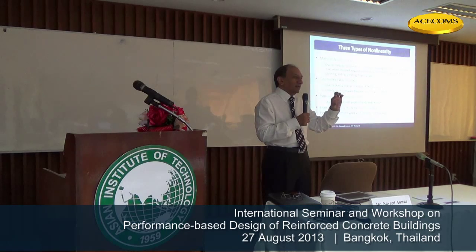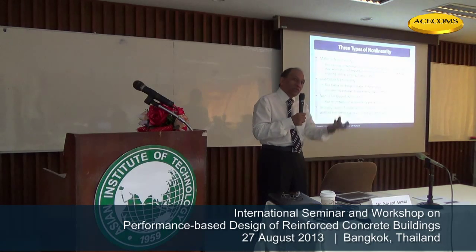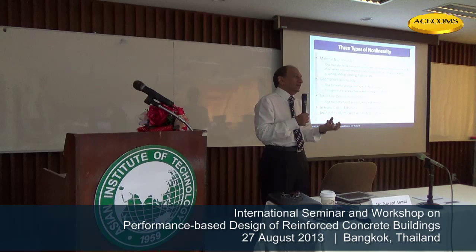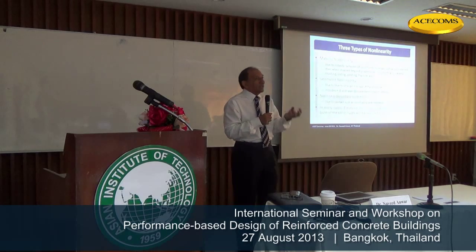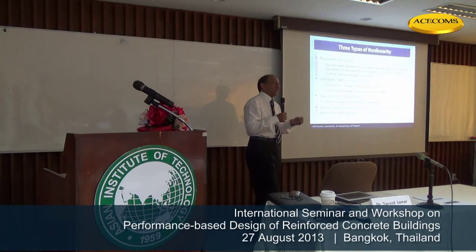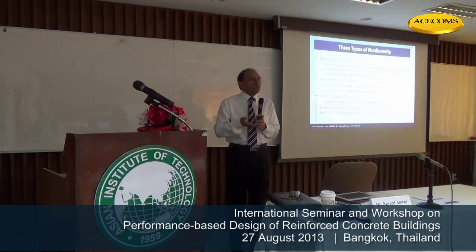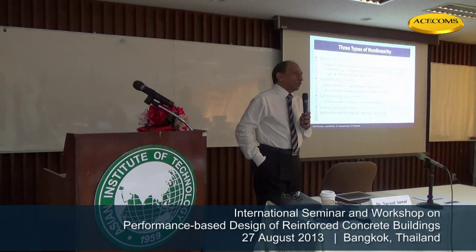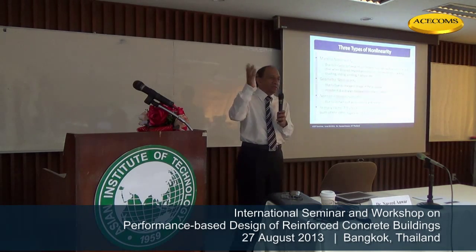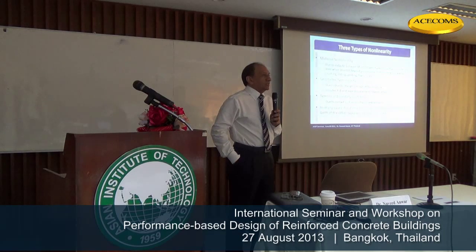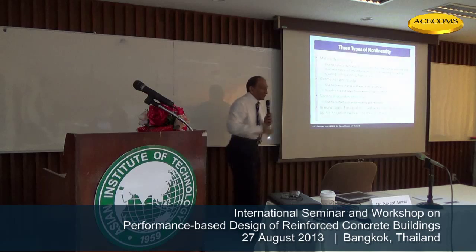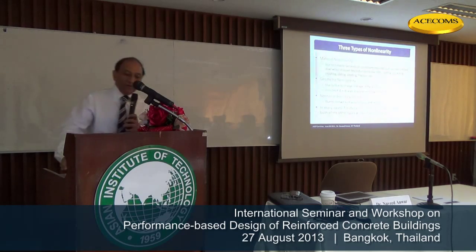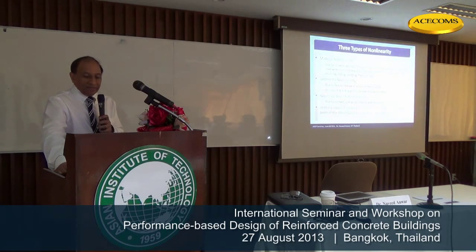That must be modeled. In a normal model, the foundation will pull the structure down. In reality, it cannot pull it down, unless it is a tension pile or something. So in that case, we need to model the separation or the lift off of the foundation, and so on. Expansion joints and so many separations, boundaries need to be modeled. They are all nonlinear. So that means nonlinearity we can divide into material, geometric, and boundary.